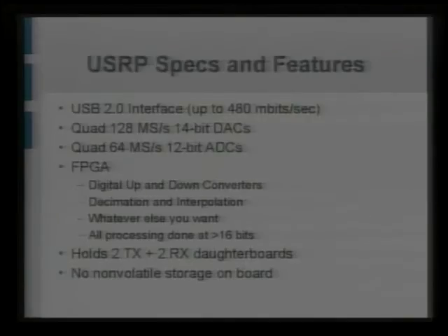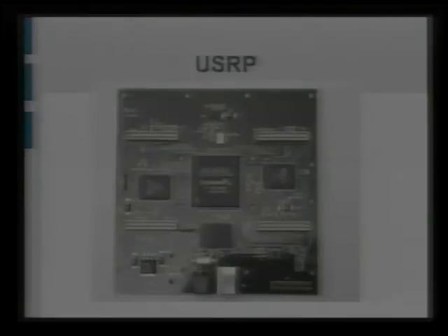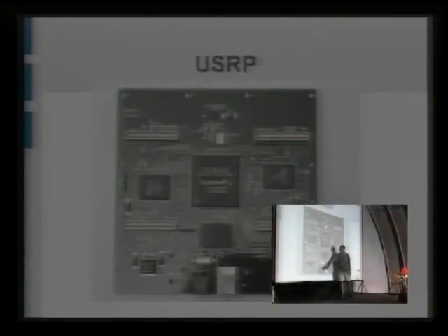And this is somewhat out of order. But to tell you what the USRP is overall, actually, it would be best if I do the picture first. Okay. This is the USRP. And so the way this works, here's the USB 2 connector that connects to your computer. This is power. This is the USB 2 interface chip. And so this communicates directly with the computer, and it has its own high-speed bus that talks to the FPGA. The FPGA in this case is an Altera Cyclone.